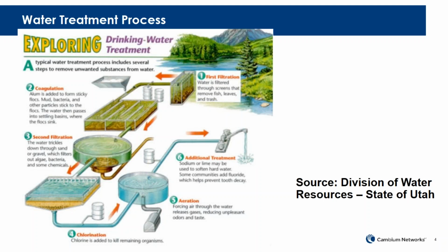And so what I kind of want you to think about is that whole flow of water all the way from that pond all through these different systems, that there are a number of things that have to happen. One thing is I want to monitor the temperature, the pressure, the level of water in each of these areas. I want to monitor how much water is flowing through each of these areas. And then I also want to be able to turn on and off pumps in these areas so I can stop the flow or start the flow at any point in this process. So traditionally you might do that with a bunch of valves that you have to send somebody out to the field, turn the valve, take a look how is the flow working, turn those valves.